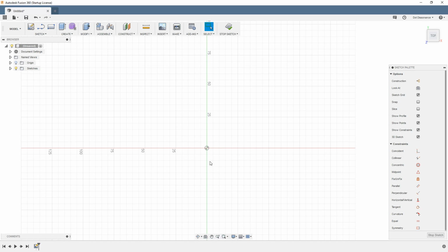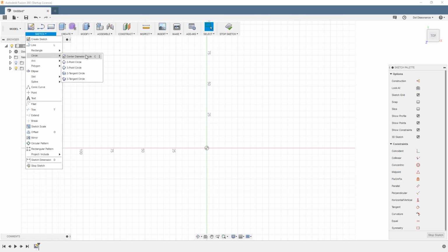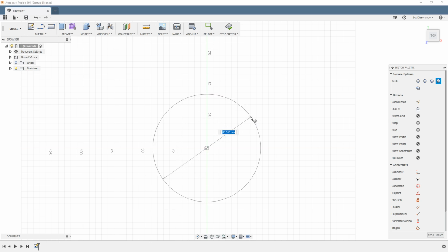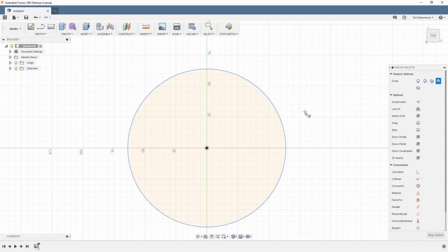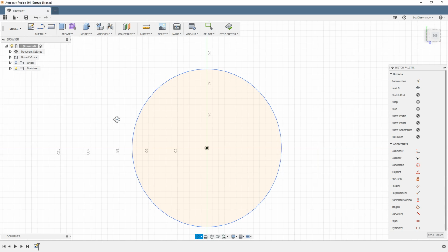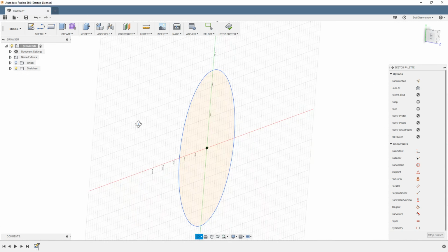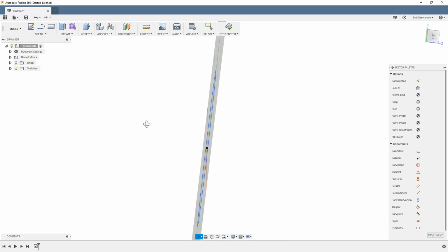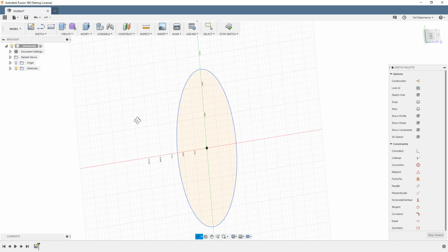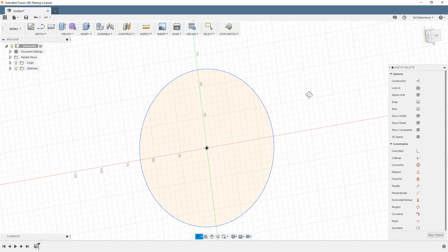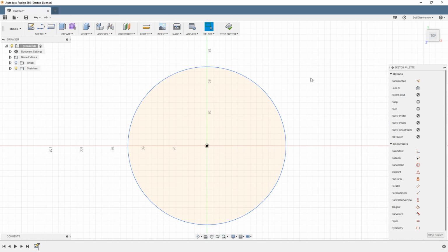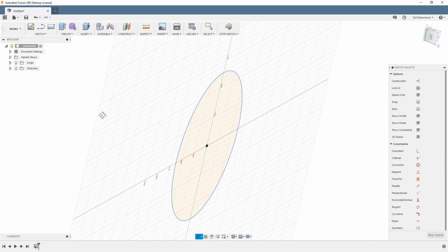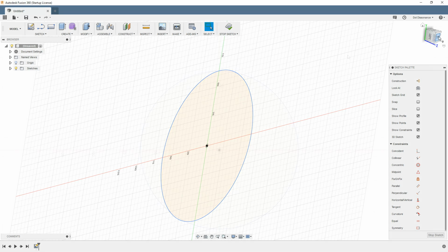It flips up into our screen, and now we're looking down at it, where I can go ahead and do kind of like we did before. I can make a circle here, click, snap on the center, click, there's my circle. I hit escape to stop the tool, and if I turn it sideways, you can see that I am still in a three-dimensional world. It just flattens you out onto the grid on this two-dimensional plane out of convenience. All right, so I'll turn it a little bit sideways. I look at my cube over here, I hit top, and it flattens me back out. Remember that about the cube. Don't make yourself suffer trying to work on something sideways if you don't need to.